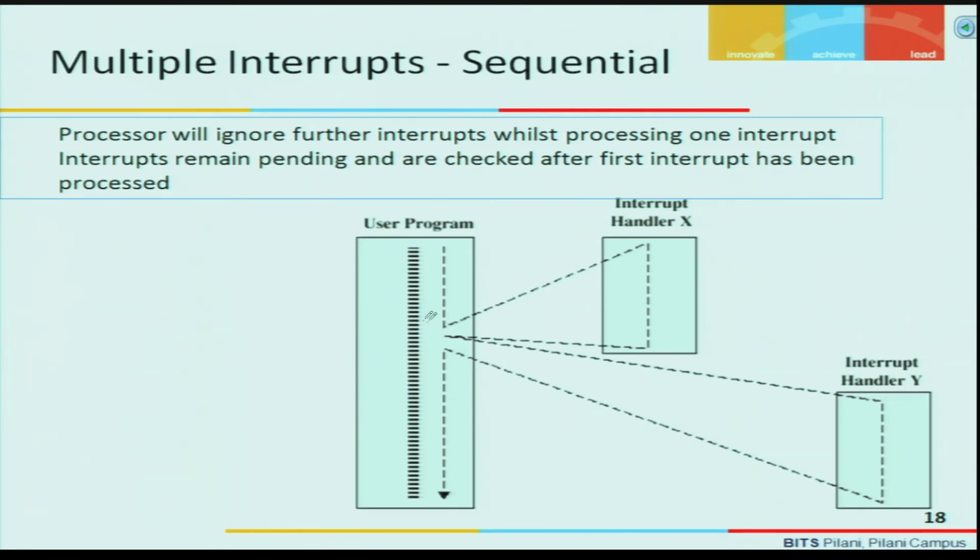Here a user program is running, and an interrupt is generated by some module. Through either software polling or hardware polling, the processor will jump to identify the device. Hardware polling is fast compared to software polling, because a hardware signal is processed faster than program execution, since the ISR is nothing but a program. It reads instruction by instruction, checking which device has generated the interrupt. The device which generated the signal will respond, and then it will be handled. In the case of hardware, it is done through a hardware circuit.